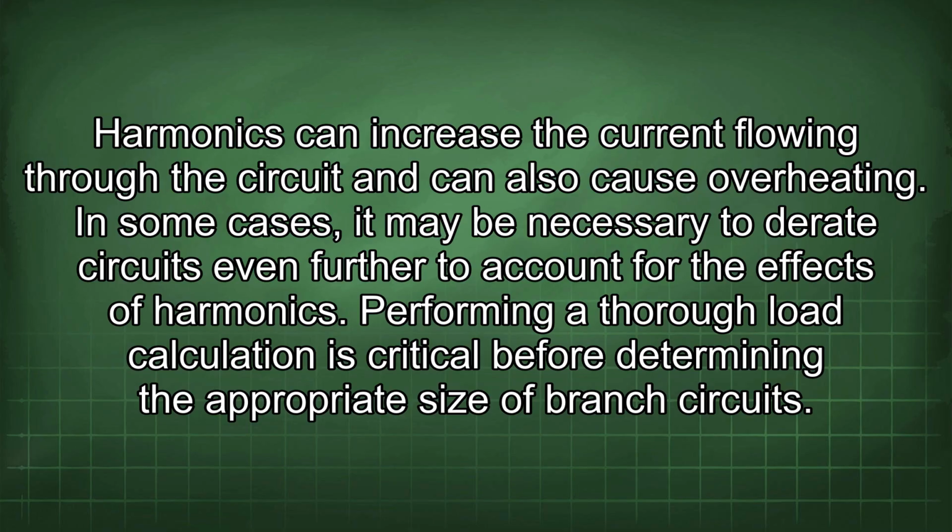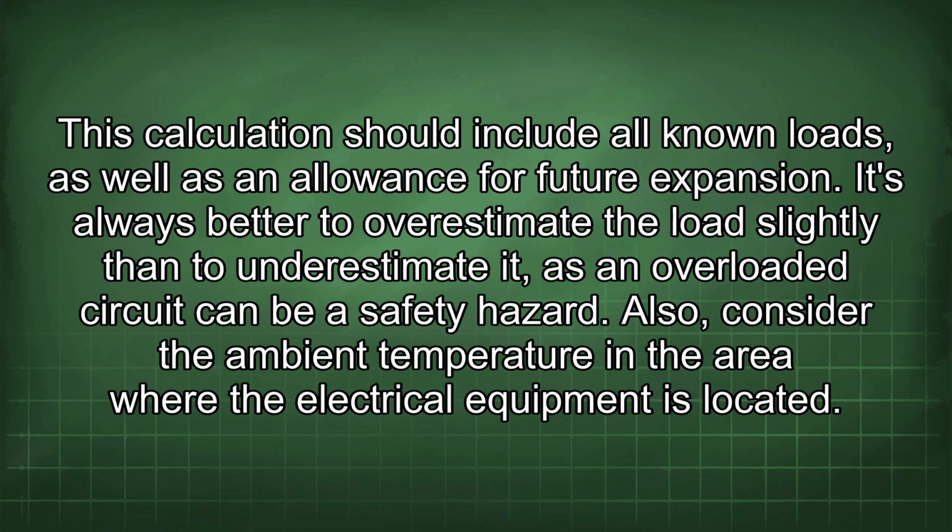Performing a thorough load calculation is critical before determining the appropriate size of branch circuits. This calculation should include all known loads, as well as an allowance for future expansion. It's always better to overestimate the load slightly than to underestimate it, as an overloaded circuit can be a safety hazard. Also, consider the ambient temperature in the area where the electrical equipment is located.